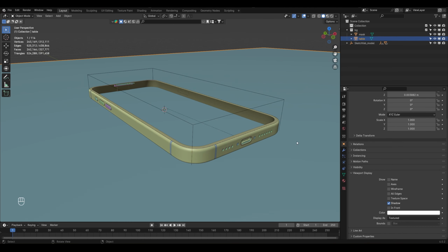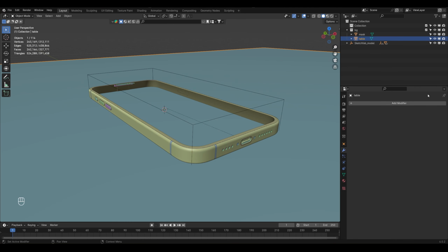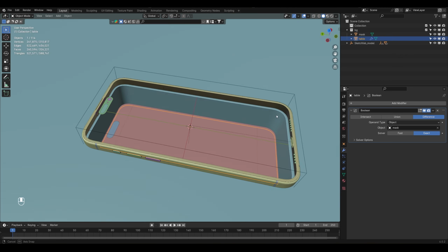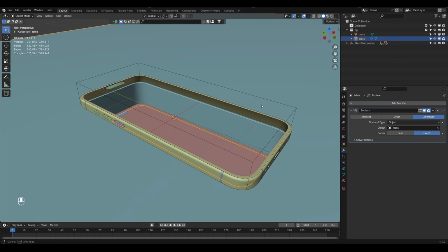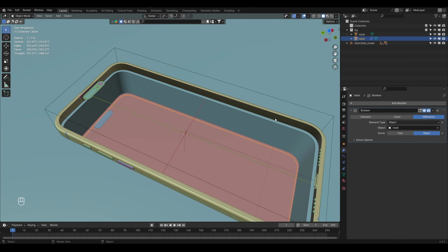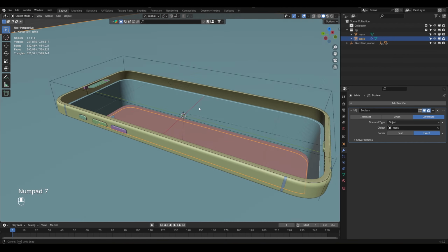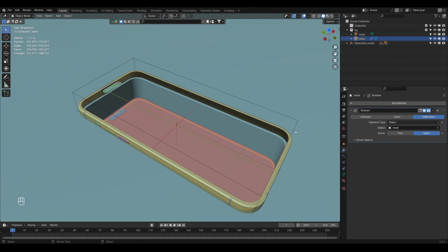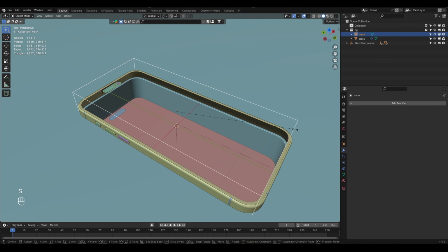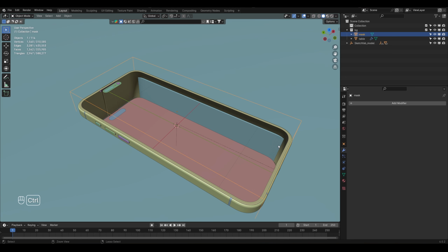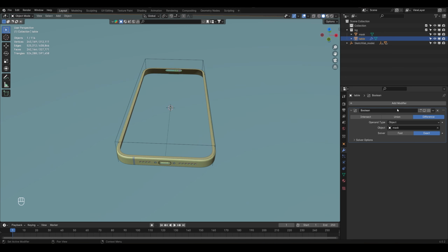And then I will select this table and go to the modifier tab, and here go to the generate and choose boolean and select this mask part, and you will see we have good looking space going on. And if you feel there is still some room left, you can just scale this and this will fix that issue. Let me disable this for now.